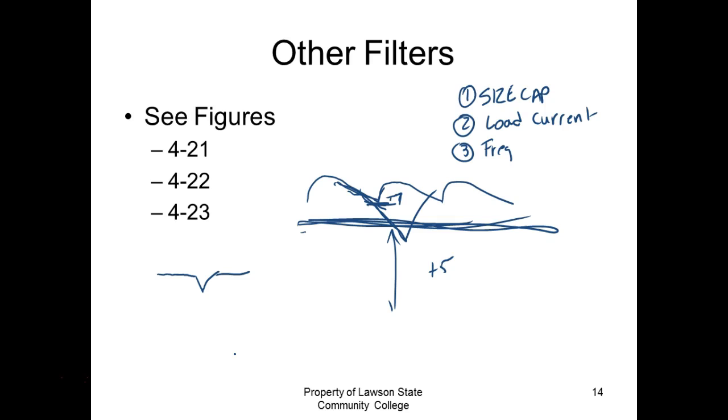The top one, we have no problem. So what determines how fast that thing slopes down would be what size capacitor, right? We'll leave the frequency off because our frequency is always going to be 60 cycles. So it's the size of the capacitor, and then also how much load you put on there. The more current load you have, those valleys start dropping down because the capacitor discharges faster. And if it ever dips down below where your regulator's regulating, it can't regulate anymore.